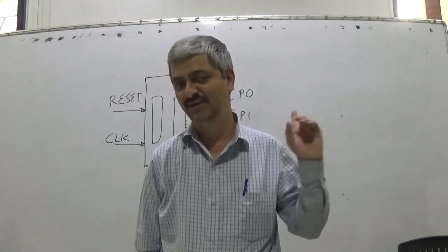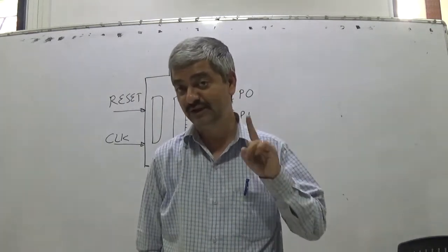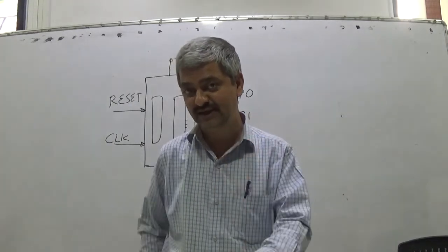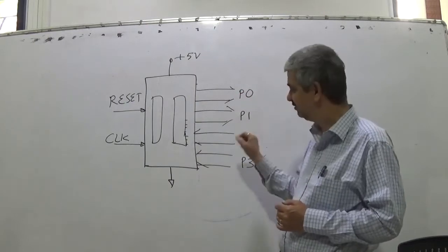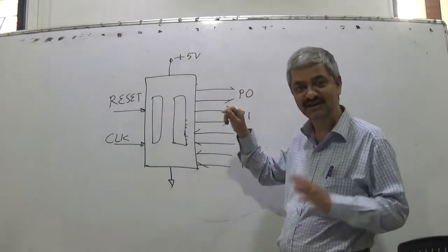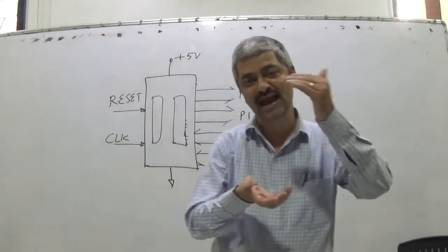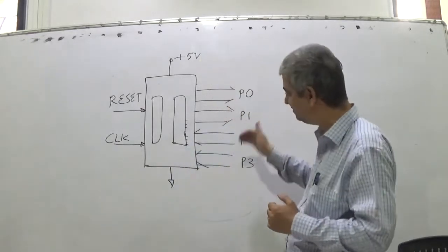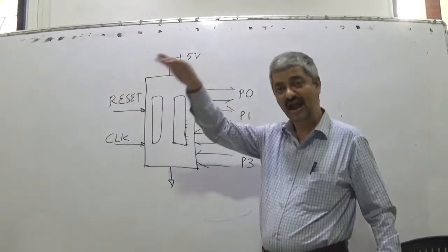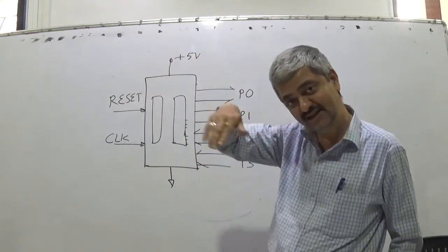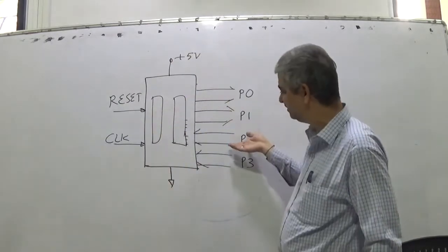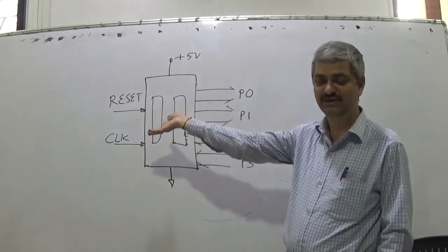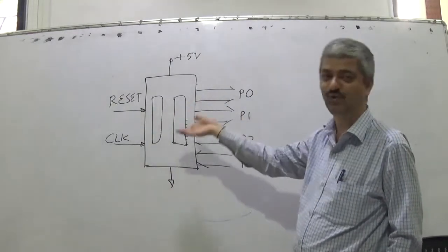That's all. Now if the location which CPU can read is that location which I can change using switches, in that case, whatever I set on these pins, CPU will read that. And what I will write in the program is, if one particular pin is 0, what should be done? If one particular pin is 1, what should be done?